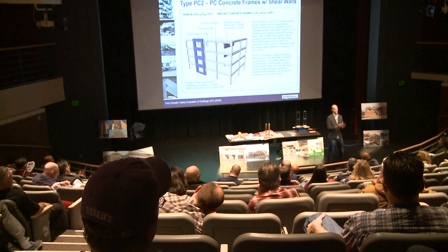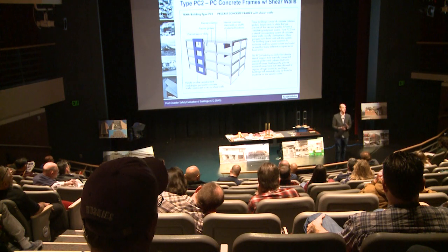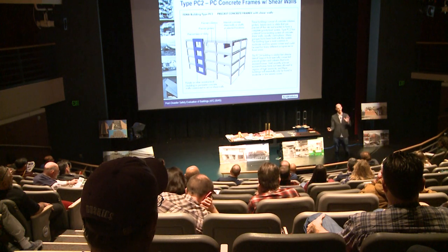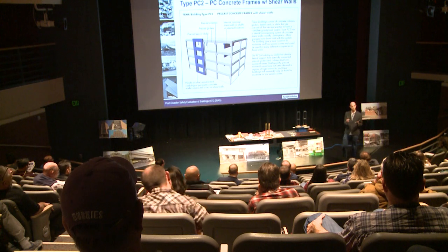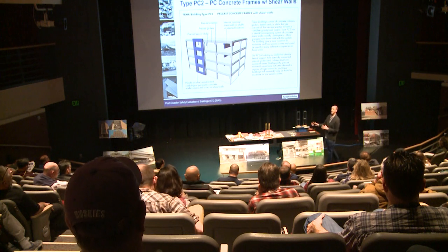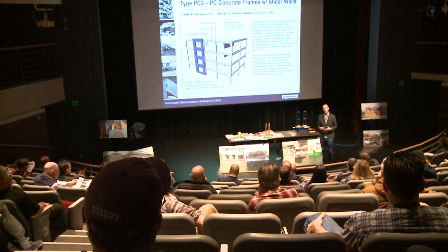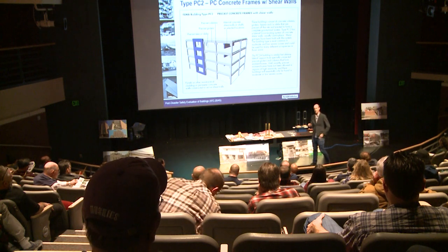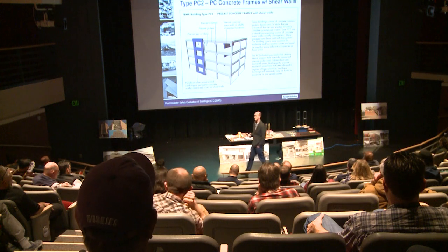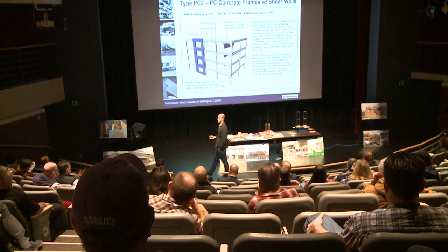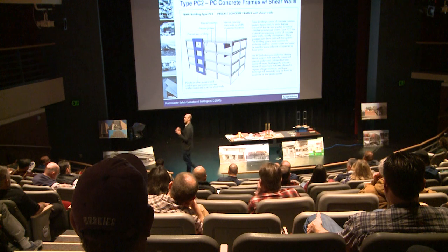What about fully grouted reinforced masonry, like CMU wall buildings, like a Costco? It can actually be relatively ductile, maybe not as ductile, but it can be pretty ductile. So it all depends. I say that to say, what about precast concrete? It all depends on the connections.